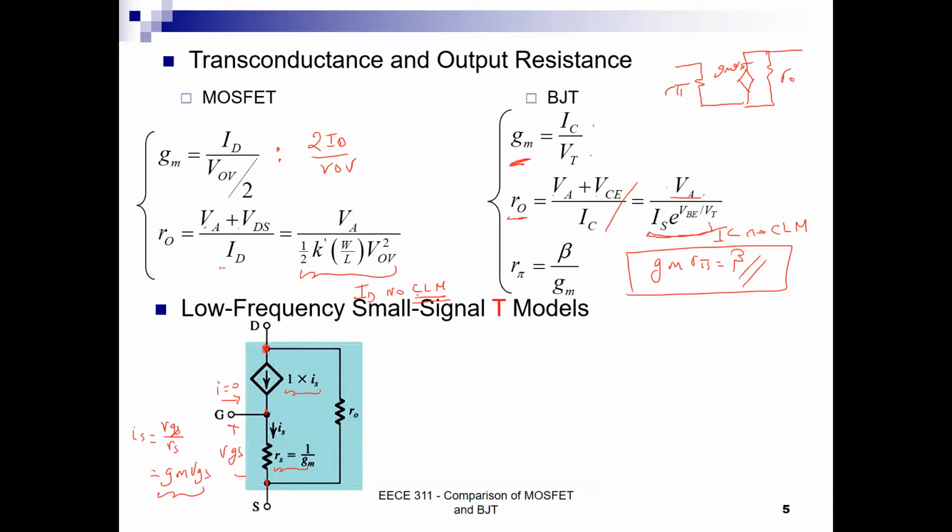We will take it when we study it in context. RO remains between the drain and the source nodes. The way we use any of these pi models, or the T model, is that we take the transistor and plug in this specific model instead of the drain, gate, source, and we connect the rest of the circuitry around it like we spoke last time.